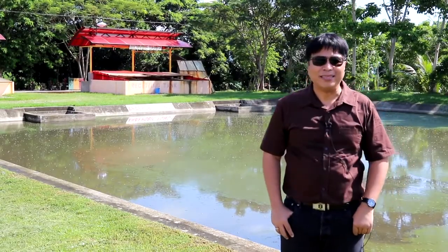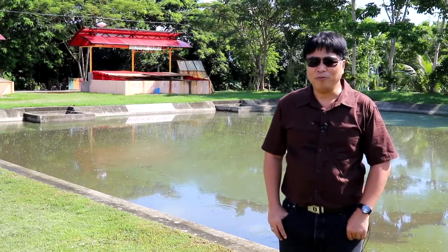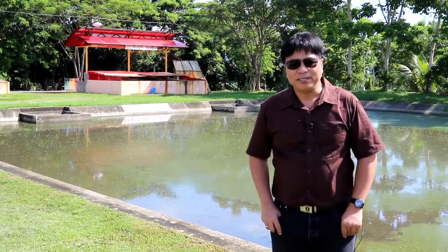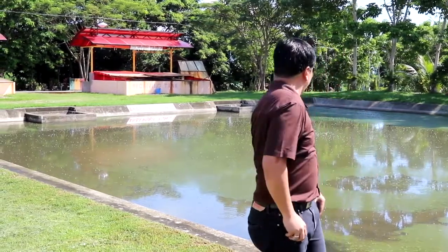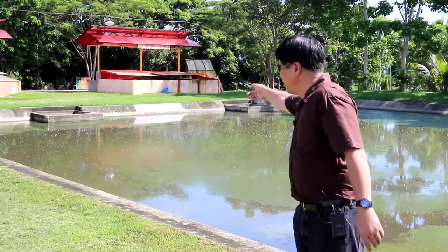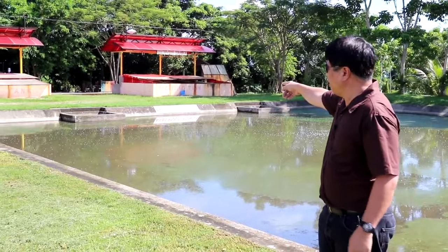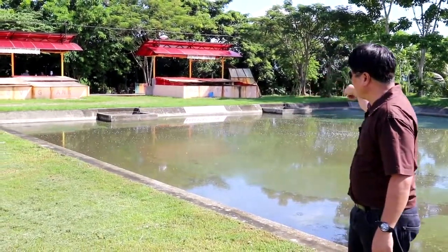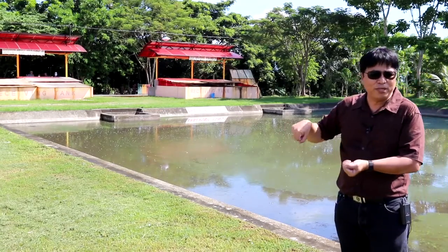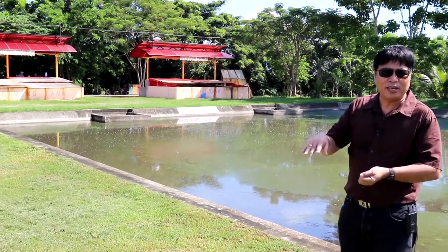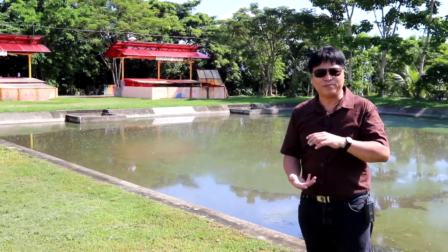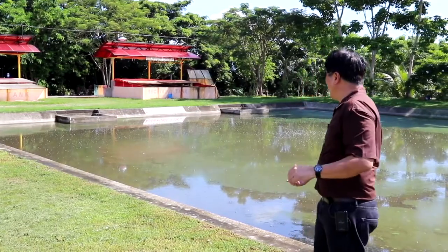We go to the first pond. The liquid part and some of the organics that pass through the screening part overflow into this anaerobic pond. You will notice immediately a receiving baffle there to avoid the entry of the liquid to the surface. It's actually at the lower bottom, around 0.6 meters from the surface water.